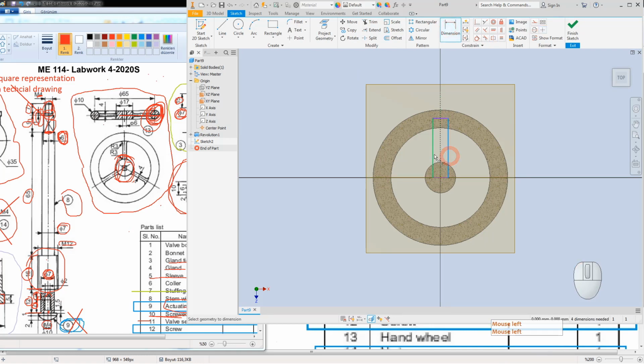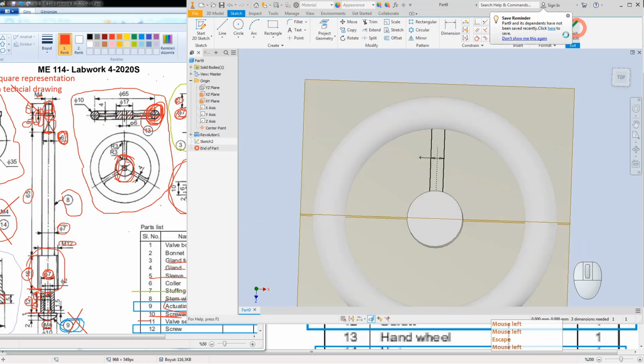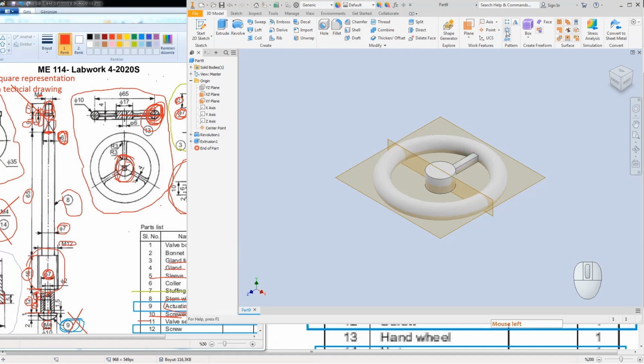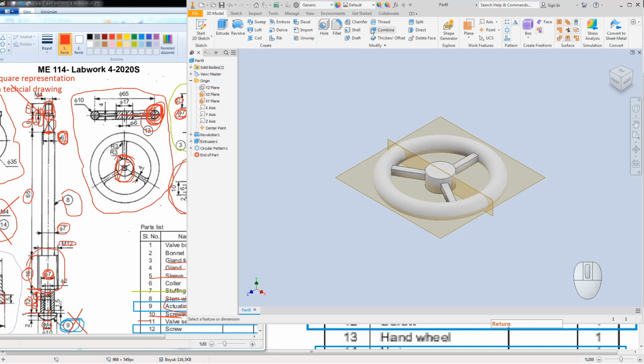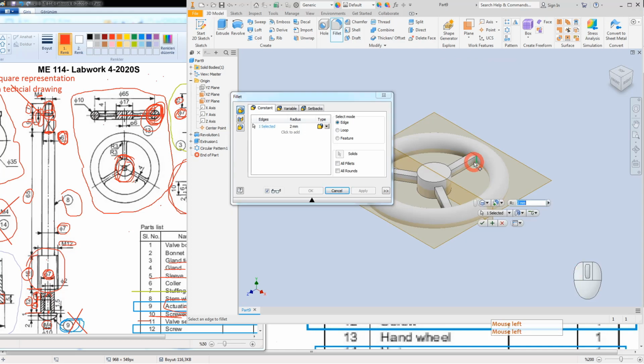The thickness of this arm is 4 millimeters, and it sticks to the inside of this figure here. Also, it is kept inside. This is enough for this part. Have the extrusion with 4 millimeter thickness. Again, first the distance extrusion length with 4. Do not forget to change the symmetric condition here. I will make a copy of these two arms around this. I need 3 copies like this. Also, I will make the fillets, which are 3 millimeters. This one.